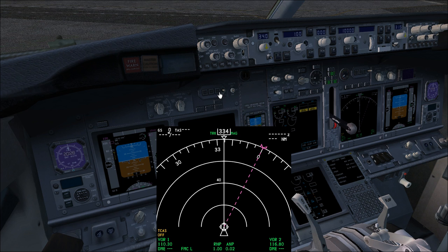Those switches turn on information on the navigation display. The first switch is about weather radar, and as you can see we have weather indication here. We can turn it on and off. Then we have station. Station shows all available stations around the airport. As you can see, I select it and you can see all the indications. We have different indicators for every station. For example, this is only a VOR, while this is a VOR DME station. We have also the navaid's name in 3 letter indications, and it also shows NDBs. The station can be set off.